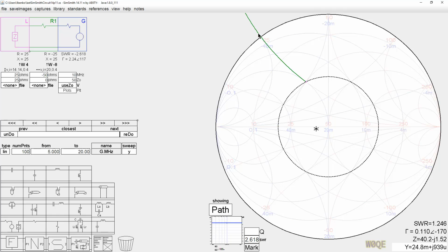These lines are outside the Smith chart. The Smith chart is inside the Smith chart. Are all impedances possible with a real part greater than or equal to 0. So from 0 to infinity, plus or minus j, minus infinity to plus infinity, all are mapped in this area. If R is negative, the real part is negative, you're outside here somewhere. And there's no reason you can't be outside. You generally are not outside in a passive circuit, or I don't think you can be outside in a passive circuit, but in an active circuit like an oscillator, you can easily be outside. That wasn't the point of this.